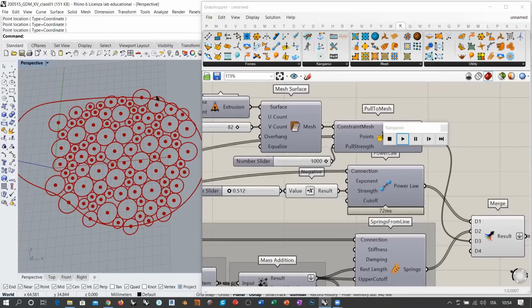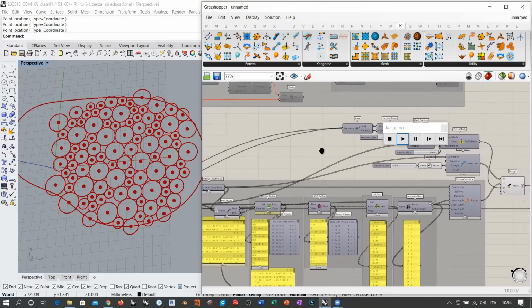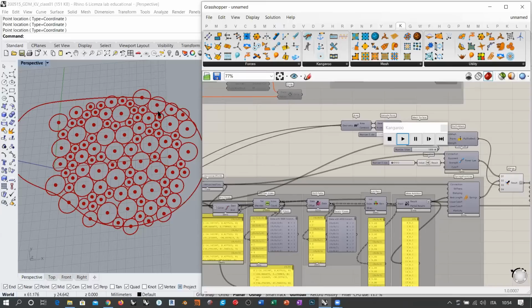So if you want the circles to stay inside the region, what you can do is basically create an offset of your initial curve. So you say, I want to stay inside, and program the offset to use the larger radius that you are considering.